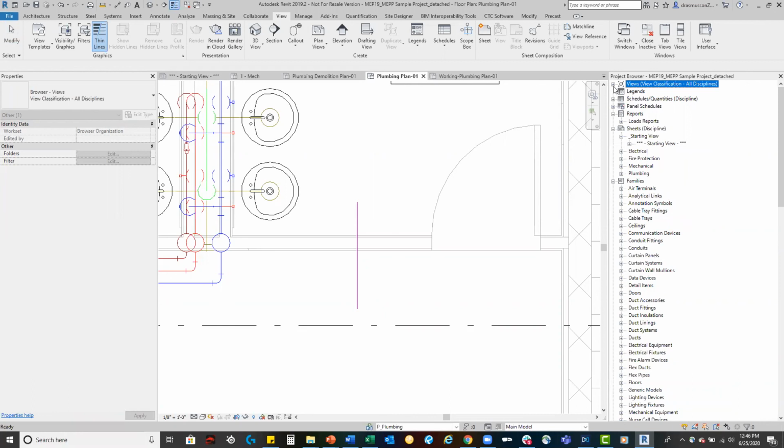You would group that, and then you would simply place it every place that specific unit showed up in the plan. Then I only had to adjust one group and all the other groups would adjust, okay? It's a pretty slick workflow until we have to go and connect in domains and ungroup everything. But it's a nice workflow as we're going through, let's say, a DD phase and even earlier times in a CD phase.